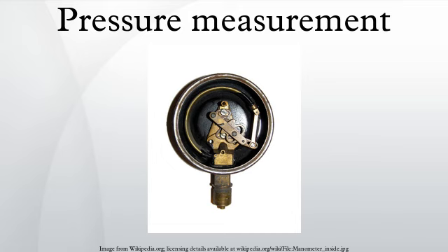Moving parts. Stationary end of Bourdon tube. This communicates with the inlet pipe through the receiver block. Moving end of Bourdon tube. This end is sealed. Pivot and pivot pin. Link joining pivot pin to lever with pins to allow joint rotation. Lever. This is an extension of the sector gear. Sector gear axle pin. Sector gear. Indicator needle axle. This is a spur gear that engages the sector gear and extends through the face to drive the indicator needle.